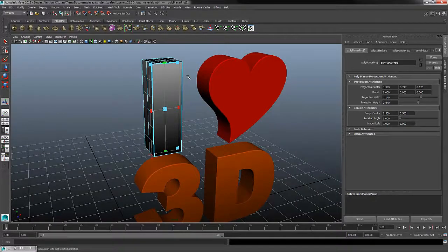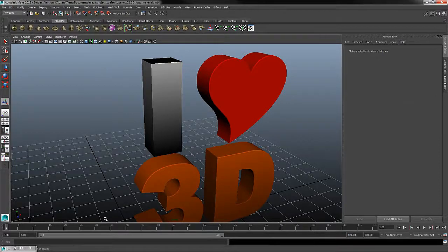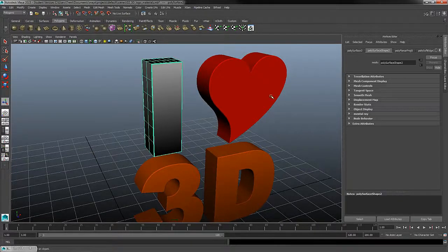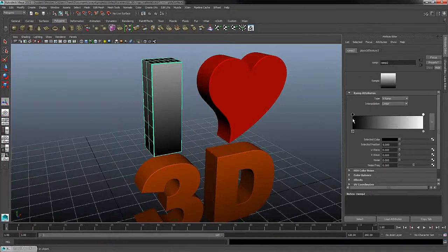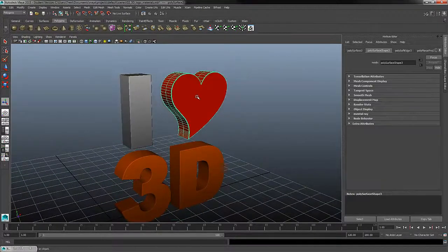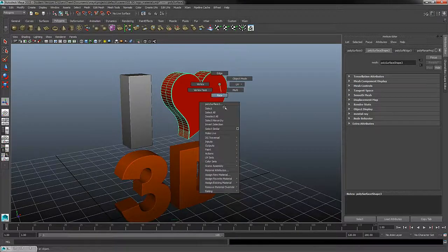So to complete the operation, remember the steps. Right click, go to object mode, and select away from the object. So we'll edit the material attributes once more. I'll come back to this black color, and I'll just lighten that up to more of a gray on the bottom of my object. Okay, rinse and repeat one more time to just really reinforce how that procedure works.